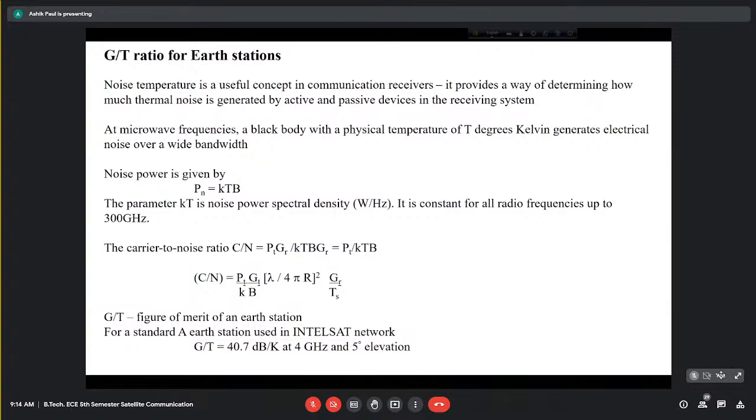Then comes the detector, which is very often a square law detector. And thereafter, you go on to the low pass filter integrator stage, and finally to some output amplifier before you send that output to some kind of a display or a final recording stage. Okay, so these are in a nutshell the basic block diagrams of a super heterodyne receiver or a communication receiver.